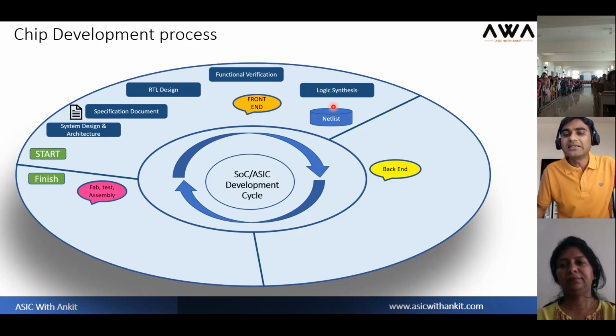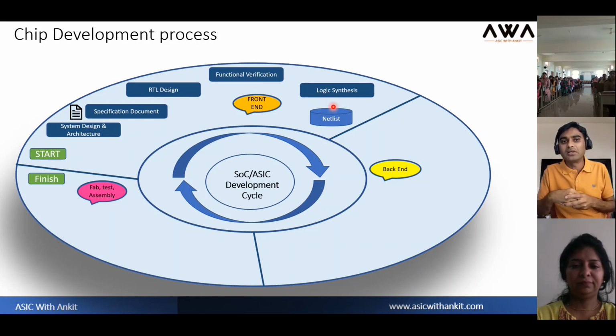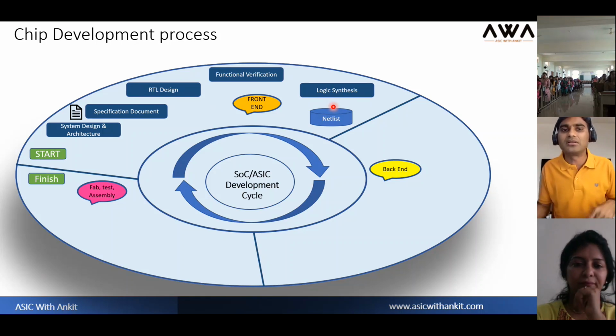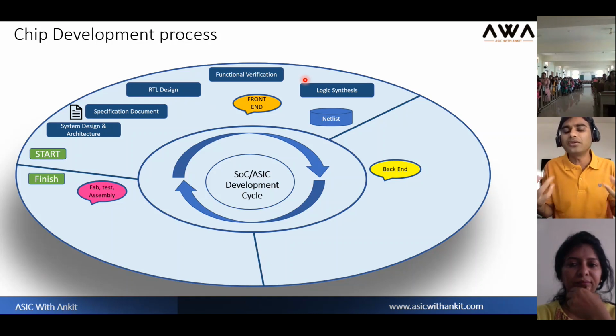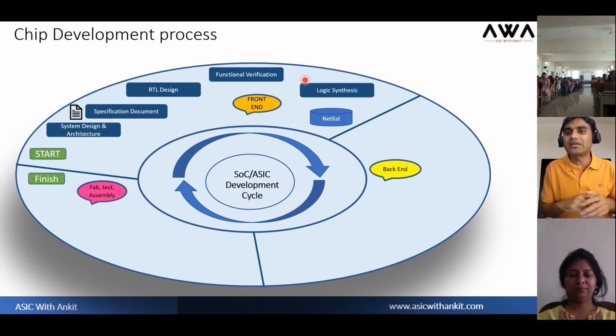Logic synthesis is nothing but converting your RTL design into gates, or the gate level design, which will give you an idea of how many gates your design gets converted into, with respect to the complexity that you are designing. With that, you get a netlist, and you run gate level simulations to make sure a lot of different functionalities have been taken care of, and that the gates are all good with respect to the checks. So this is all the front end phase of the chip development cycle.